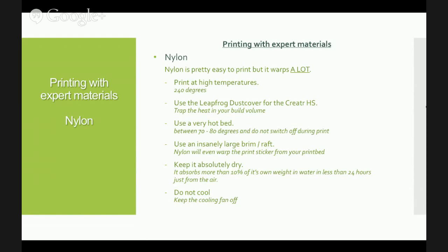And again, also same as PVA, but even more, keep the nylon absolutely dry. It absorbs more than 10% of its own weight in water in less than 24 hours, just from the air. So if you let it sit for 24 hours on a shelf without anything, it will absorb 10% of its own weight in water.